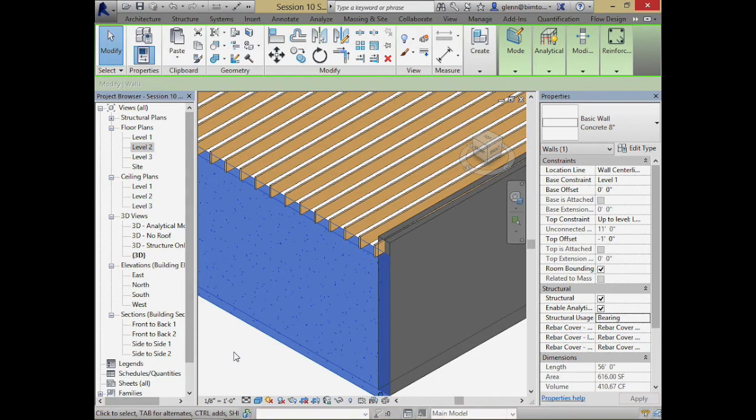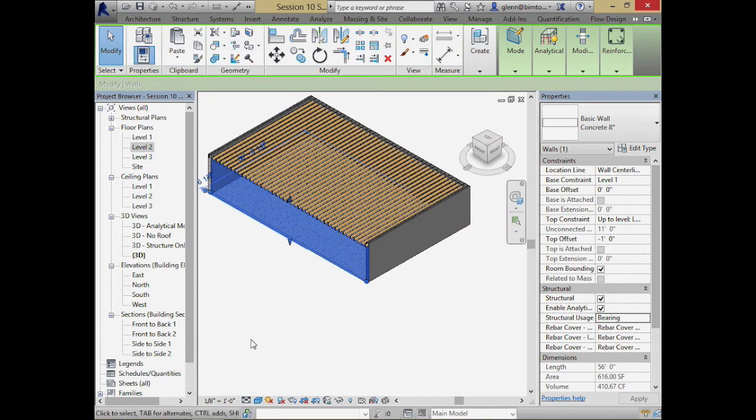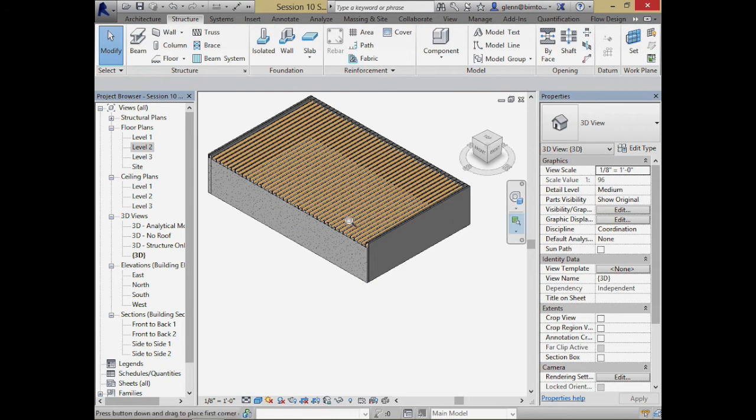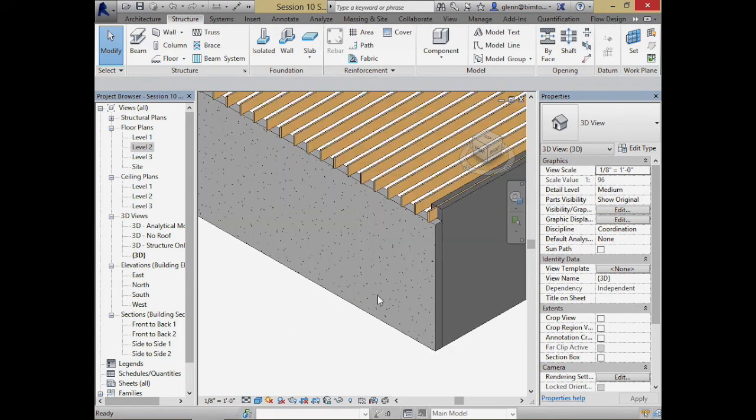So in terms of these exterior materials, walls actually can support things. Concrete's very, very good. It has a very high bearing capacity. Wood, not so much. I think the limit is if you have over 2,000 pounds coming on the end, and that seems very high. You basically have to make sure that it's not just sitting on the wall. You have to explicitly put a post in the wall.